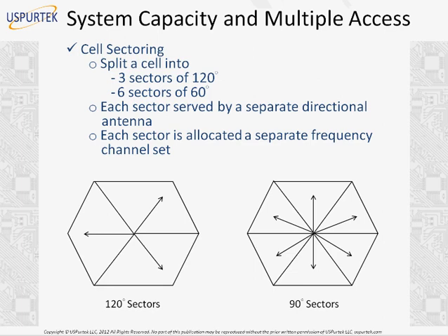But if you have directional antennas, let's say 3 antennas divided into sectors of 120 degrees each, then for each antenna the interference can enter only from one side. So we have reduced the co-channel interference this way by providing 3 different directional antennas and dividing the cell into 3 sectors of 120 degrees each. That is an additional benefit. So this is the most widely deployed technique used in current 3G and 4G networks, to reduce co-channel interference so that we can maximize wireless system capacity.